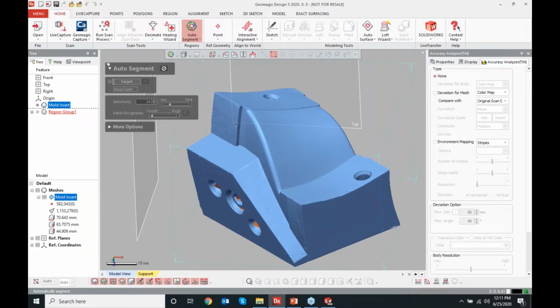So it's going to disassemble the model, essentially finding all of the component geometries on it. It's going to assign a color to those geometries that makes it a little bit easier for me to view the model and interact with it. It's also going to recognize what type of geometric entity that certain region is. And so that's the step that it's on right now. It's actually classifying all of the regions as either planar, cylindrical, conical, spherical, toroidal, freeform, or revolution shaped.